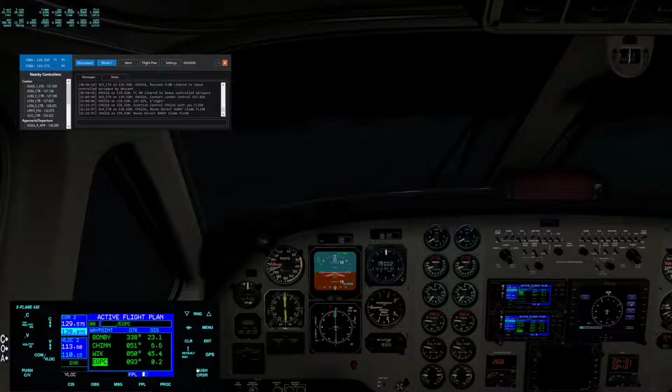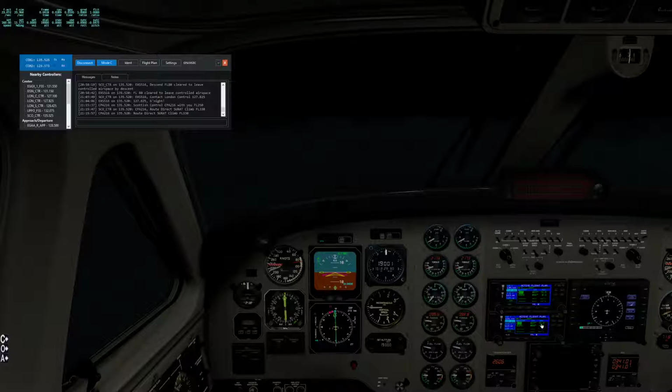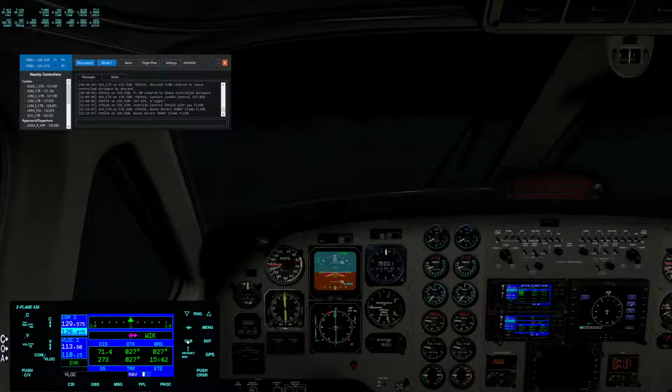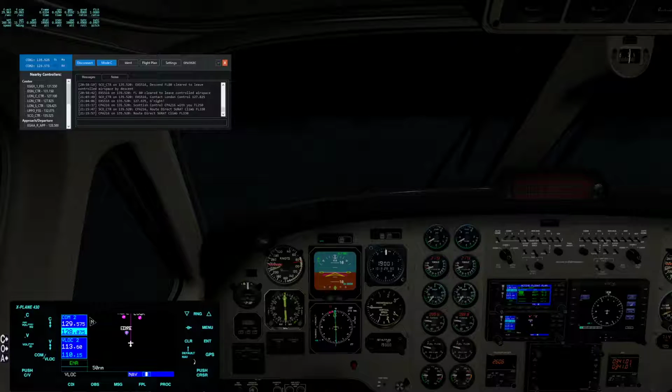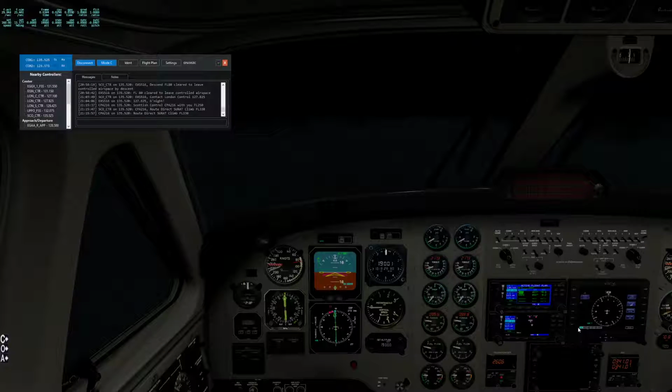So what I'm doing on the GPS is basically going to the flight plan, finding the waypoint for the Wick VOR and hitting the direct to button and activating that, which means as we're following nav, the GPS for our course on the autopilot, we will now start routing direct to Wick, and we won't be turning northwest at Inverness, which is great. But the other thing that's now thrown me...